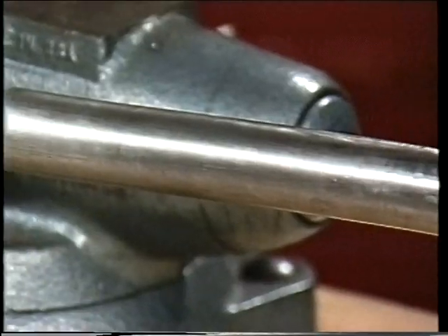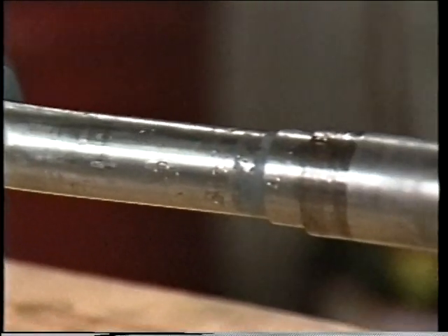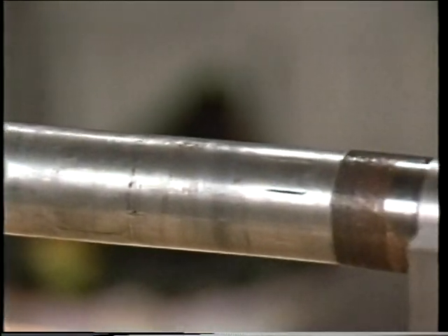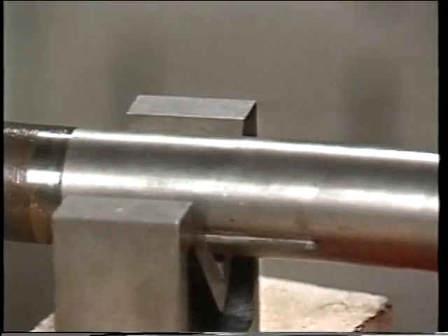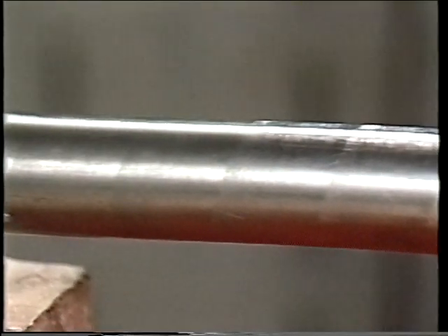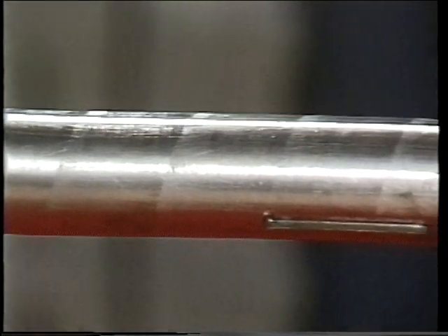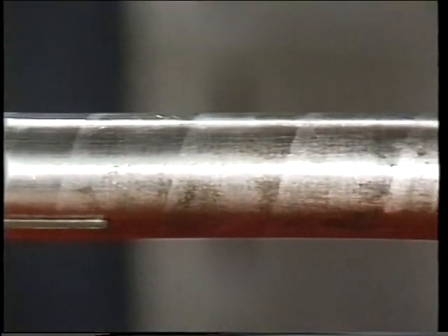If the component is perfectly balanced and aligned and has no other problems, then it may operate normally. However, if a problem exists and the component is allowed to operate at this speed, the severity of the vibration could damage or destroy the component or other components. This increased level of vibration is known as a resonance. For example, suppose the natural frequency of this shaft is 6,000 cycles per minute. If the shaft has an alignment or balance problem and is allowed to rotate at 6,000 RPMs, the vibration could become so severe that it could damage the shaft or other components.